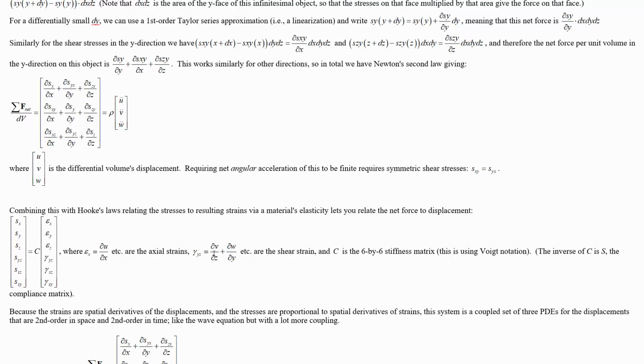That is the slope of the y displacement v in the z direction plus the slope of the z displacement w in the y direction. This gamma is the engineering shear strain. This is the one that's nicely related through this stiffness matrix here. There's another shear strain which is called true shear strain, and that accounts for rotations. Here we're concerned only with the deformation strain. This is the one that's going to respond with stresses.